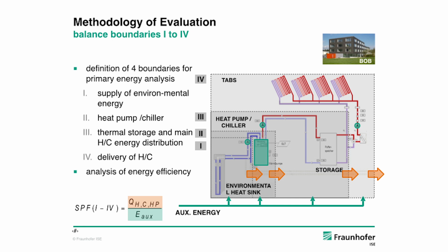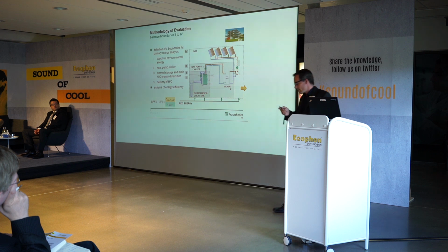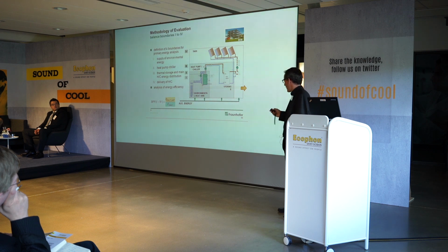And the amount of thermal energy measured from one boundary to the next, divided by the amount of electric energy that's used, gives us the seasonal performance factor of these systems. So we're able to compare different buildings and different concepts, always using the same boundaries.